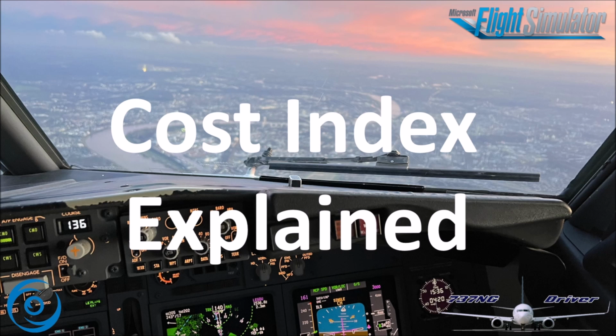Now, in general, the FMC is going to calculate the climb, cruise and descent speeds from the entered cost index. However, especially to comply with air traffic control requirements, the airspeed used during descent tends to be the most restricted of the three flight phases, and therefore it could be procedure in an airline that a general descent speed is entered and only climb and cruise are flown on the actual econ speed from the cost index.